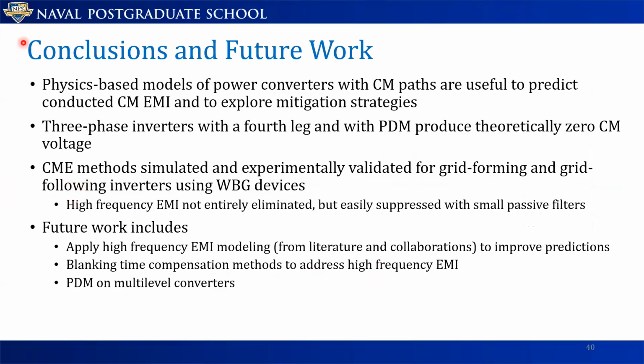So I want to conclude now by talking about the future work as well. Physics-based models are important, and of course they can be tuned depending on what you're trying to model. Then, 3-phase inverters with a 4th leg and pulse density modulation produce theoretically 0 common-mode voltage. And the common-mode elimination methods that we presented were all experimentally validated on inverters built with wide bandgap devices. And even though the high frequency EMI was not entirely eliminated, I'm talking about the EMI in the megahertz range or the high 100 kilohertz, it was easily suppressed with clip-on chokes.